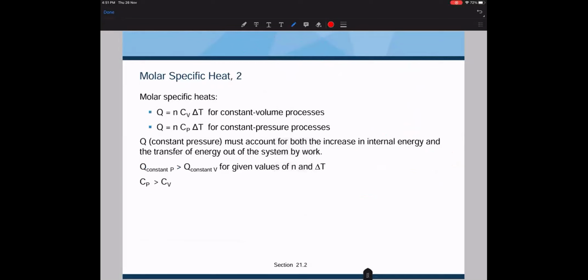So for the two processes, we would define the amount of heat energy required to bring about the temperature change. It's equal to nC delta T. Remember the specific heat we talked about in the previous lecture slides. Q is equal to mc delta T. I can't remember which page, but this equation for the specific heat has appeared, and the equation is valid for liquids and solids.